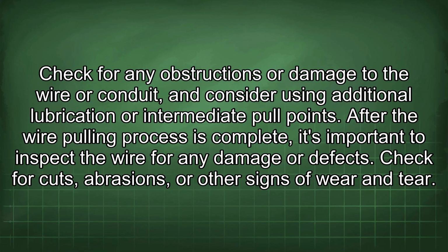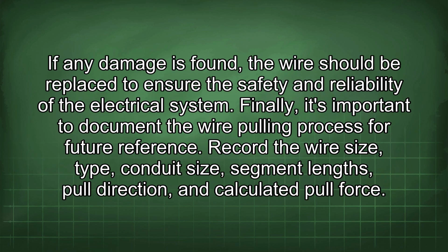After the wire pulling process is complete, it's important to inspect the wire for any damage or defects. Check for cuts, abrasions, or other signs of wear and tear. If any damage is found, the wire should be replaced to ensure the safety and reliability of the electrical system.